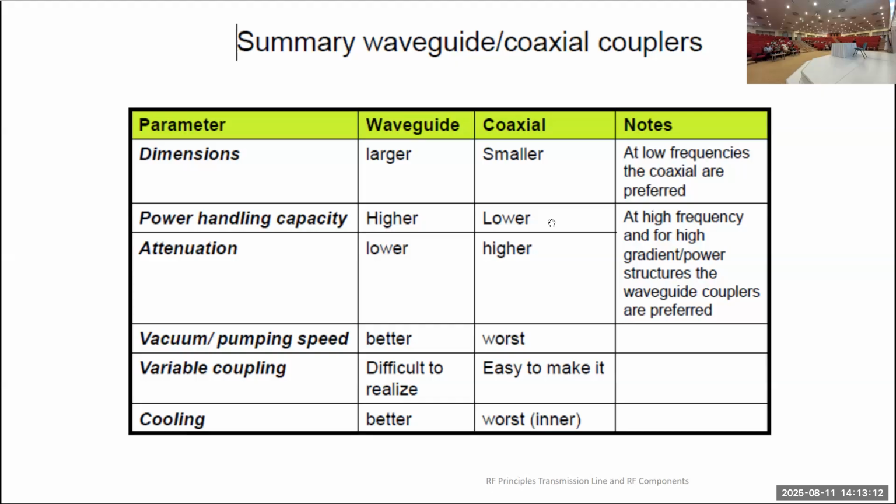To increase its power capability, it is filled with SF6 or any inert gas, which mitigates the arcing inside the waveguides. But if it is a vacuum system, with waveguides evacuated, its power carrying capacity is increased many times.